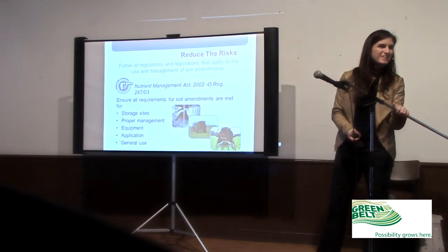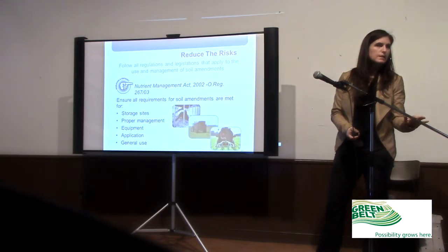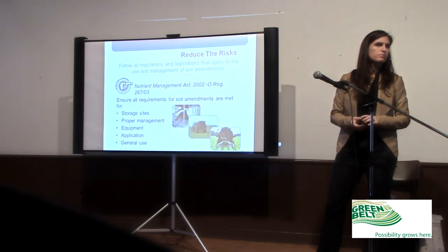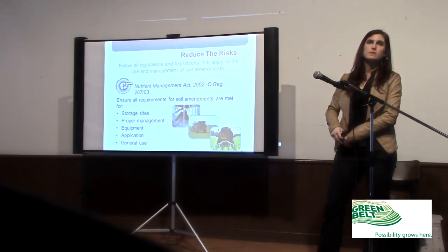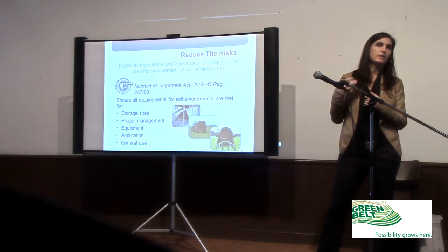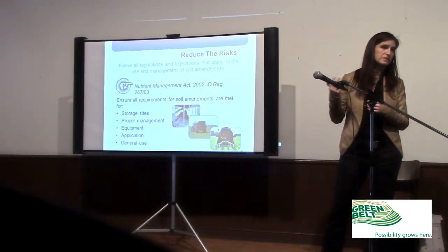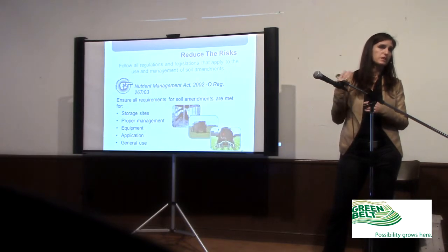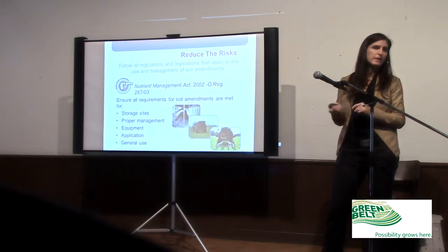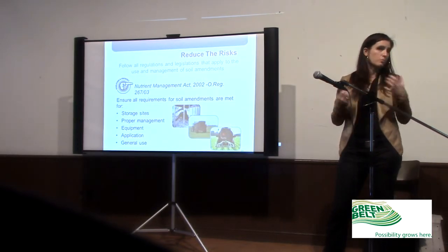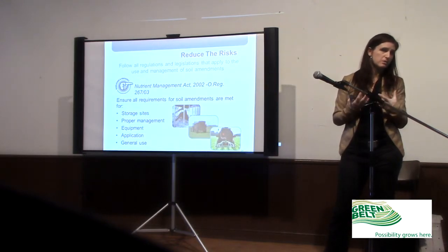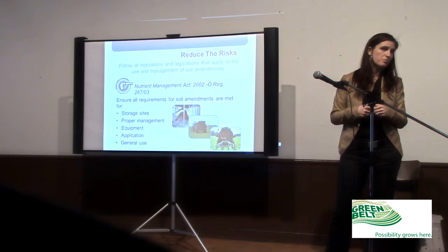Did they say what caused the fish die-off? Because with fish dying off and that kind of number, that wouldn't be from pathogenic material, that would be from either nutrient load or just clouding of the water. Yeah, they didn't really specify. In a lot of cases, it's usually caused from an algae bloom, but they did say it was from the toxicity from that runoff in the water that caused it. They didn't show an algae bloom in any of the pictures to indicate that it might be from suffocation, but they just said whatever was in the water, they linked it to the runoff, that was the direct linkage to that fish die-off.